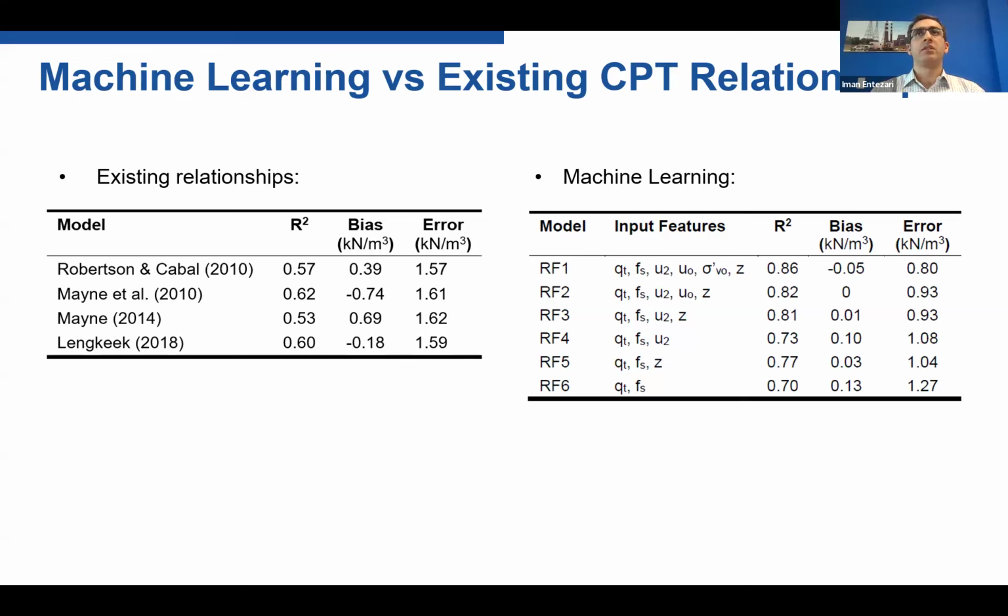Let's say in CPT modeling, what we did was that ultimately we observed roughly 5% error for estimation of soil properties, and that seems to be good enough for a lot of applications. But in some cases, you may realize that even with machine learning models and all the data you've had before, you are not getting the results that you were initially interested in. And that shows you cannot use any modeling, and you have to have other means of either lab testing or other sort of in-situ testing to get the parameters that you are interested in.